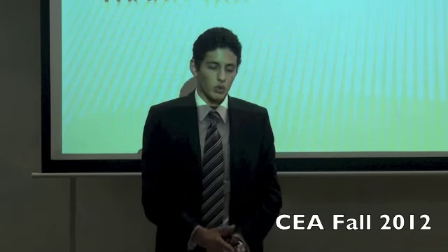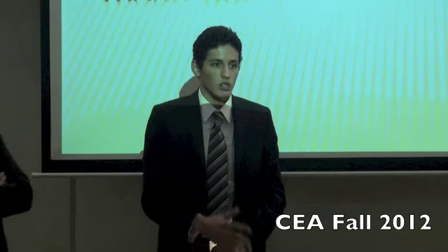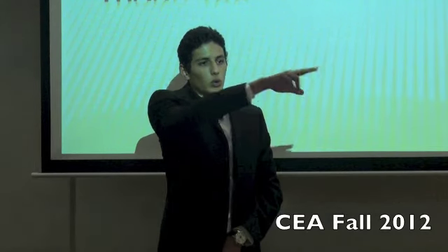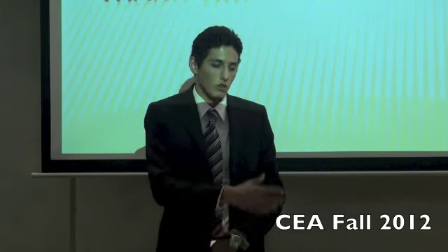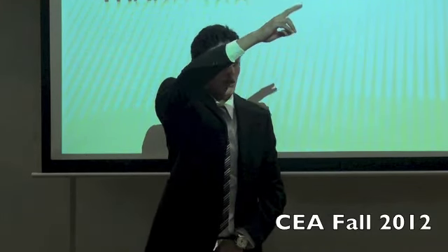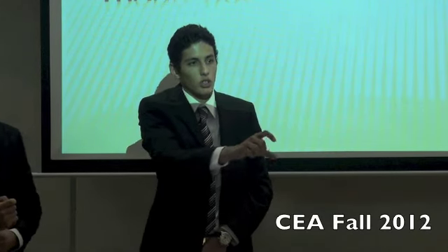Are you going to design the treatment station? No, we don't have much time for that, and we only calculate what will be treated, the amount of water, and use it for irrigation. Are you going to have enough flow from the wastewater to make the irrigation? This is our challenge, we're going to see after we calculate the irrigation demands. So if the flow is less than the irrigation demands, we need to increase the water network, some extra water for the irrigation to help with the treatment. If more, we need to have another post line going directly to the Sheikh Zayed main sewerage network, and we only supply the wastewater treatment with the amount of water needed to supply the irrigation.